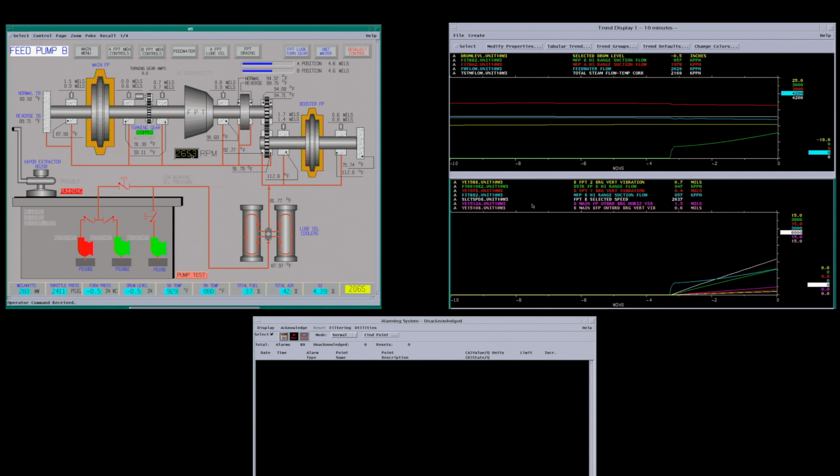We're coming up pretty good on speed, 2600 RPM. See, temperatures are starting to climb on the bearings. We're starting to get some vibrations. I'd say thrust position is critical on these things. You can damage them. Sometimes you get excess thrust on the turbines. The clearances are fairly tight. I'm thinking this one trips at 18 thousandths, and I don't know, at 22, 24, it could actually start hitting stuff inside. So there's really tight clearances in these.